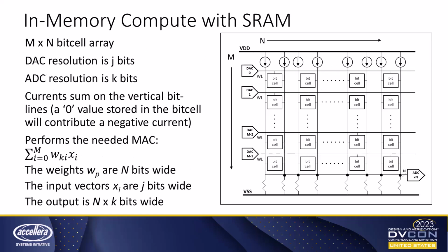So then to turn this into a complete multiplier, we just need an array of bit cells, which is what a memory is. We can apply some current sources at the tops of all the bit lines, so that we provide some bias current to feed the zeros, and then we collect current out from the ones. We can drive each row with a DAC value to provide an input vector, and each row gives us a value of, in this case, n bits.